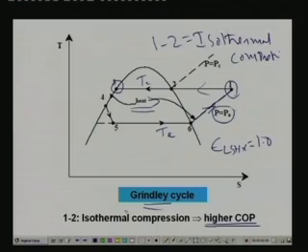What are the difficulties? The difficulties are mainly to do with achieving isothermal compression, particularly with very high speed compressors such as centrifugal compressors or reciprocating compressors. Okay. So this Grindl cycle could not be built in practice because of this problem. But still there is some interest, because using some other types of compressors such as screw type compressors, you can approach isothermal compression. So still there is some interest in this cycle.